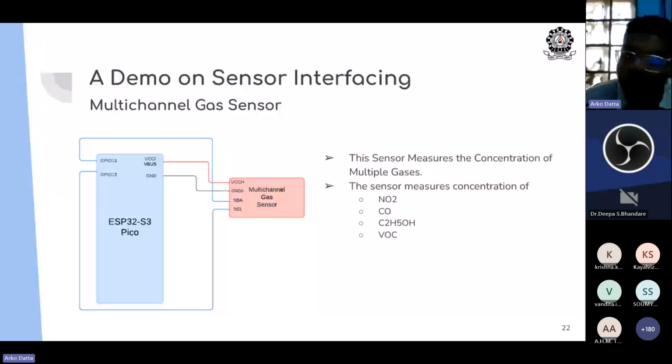Yes, sir. This can be biased by temperature, humidity, and as well as your interfering gases. So, calibration for industrial purposes or for specific purposes is required. But for general purposes, such as measuring a relative concentration, so that is my NO2 has increased suddenly, for this type of thing, we might not need to do calibration if our other factors are static. I mean, almost static.